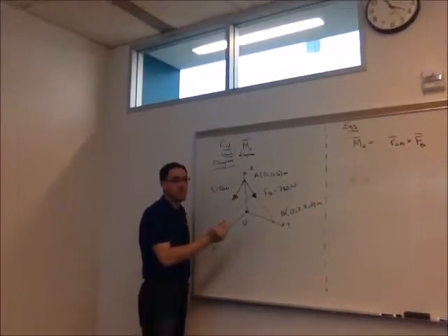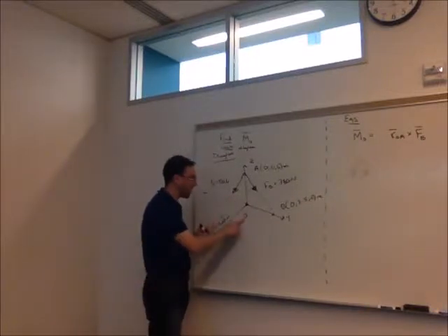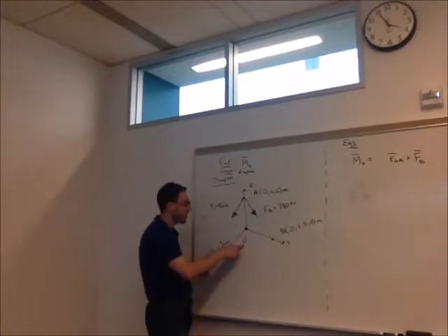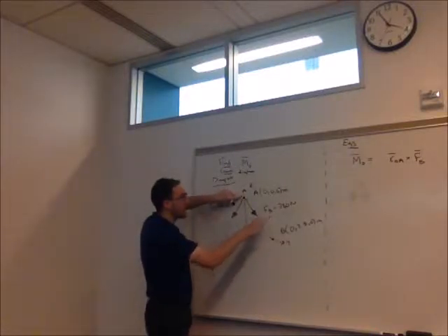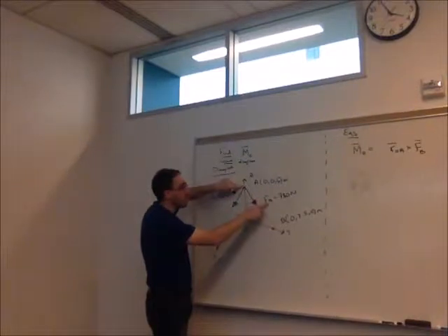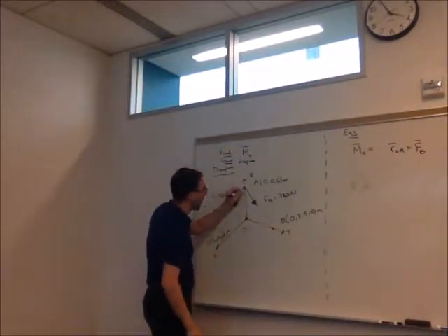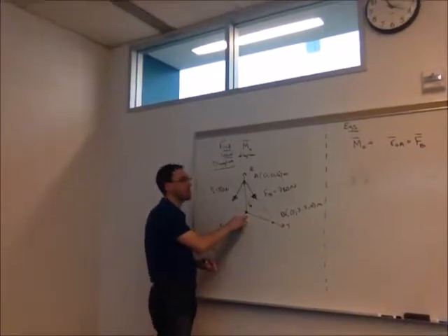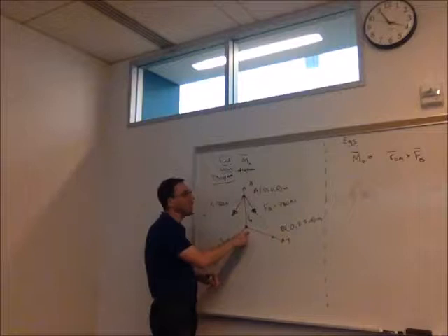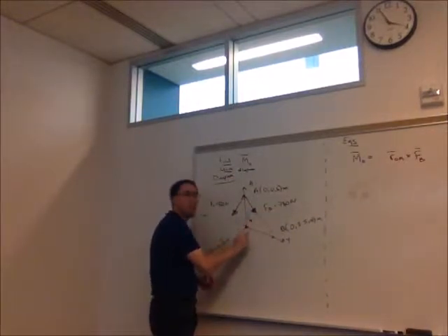So what we're using is the position vector. Again, it still points from the point we want to take the moment about, so that point O, to the point where the force is being applied. FB is being applied, even though it's named FB, at point A. So that's why we're using that ROA as our position vector. So ROA cross FB will tell us what moment is produced by vector FB around point O.